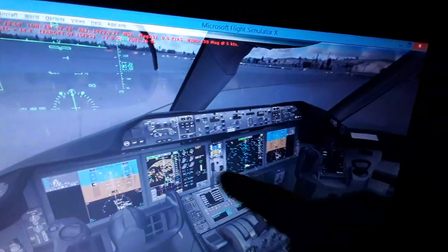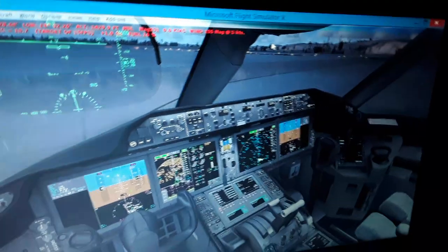We have the display in the navigation display. You can see the horizontal and the vertical profile of the flight plan here with the magenta line. You can see the terrain and weather reflections from the weather radar. You can see the red, green and yellow indications from the terrain around you using the terrain map, and the elevation of the terrain around you for warnings. We have also the display of the sea in blue, lakes and other water like rivers. We have also the airports, the waypoints, the VORs, the ADFs, the NDBs.